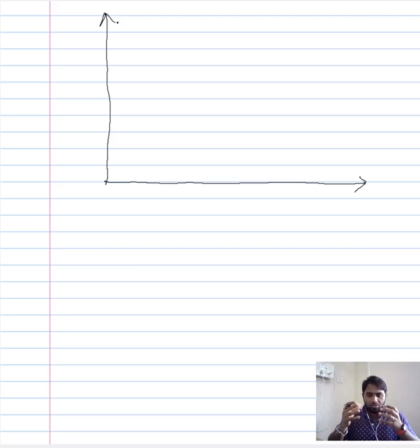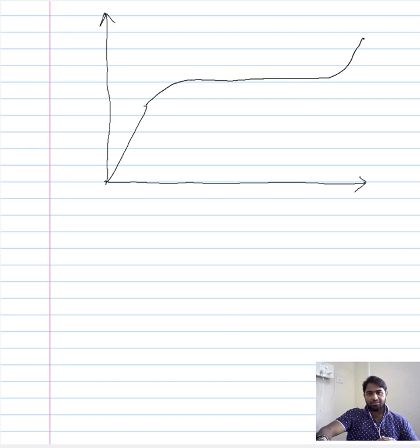And let us talk about what enabled us to categorize this curve into different stages. We did not talk much about any material aspect so far. We just saw the creep curve, the nature of it, and we categorized it. So what aided us in categorizing this curve is what we will focus on. What we have is, again, an instantaneous creep region, a transient creep region, a steady state creep region, and an accelerating creep region.